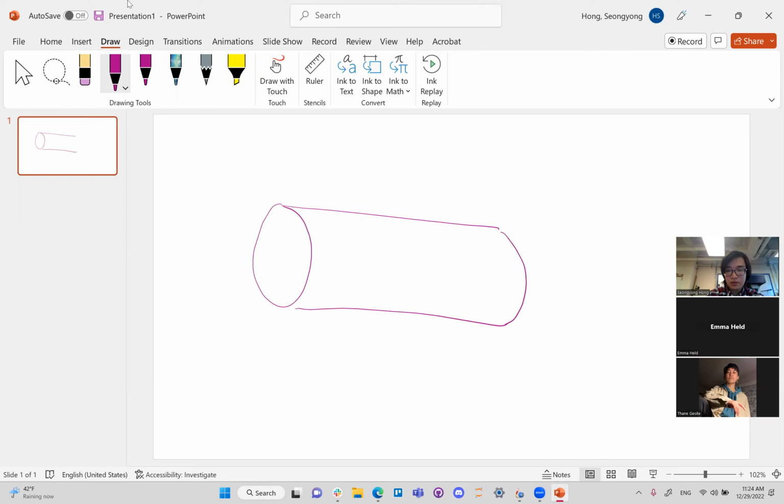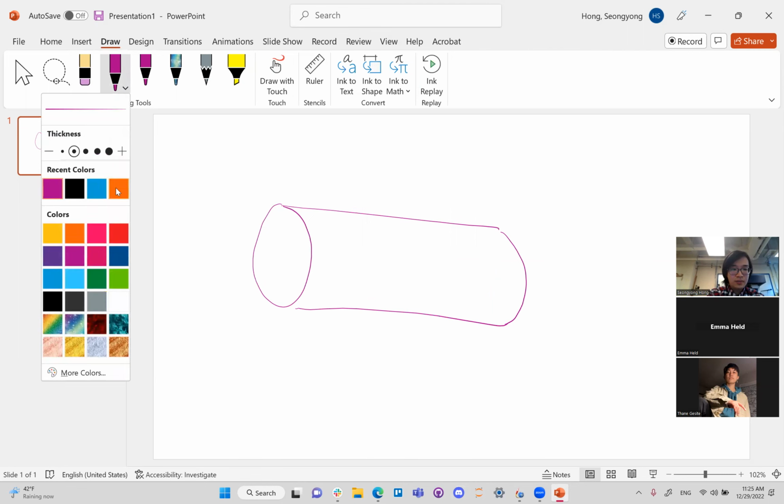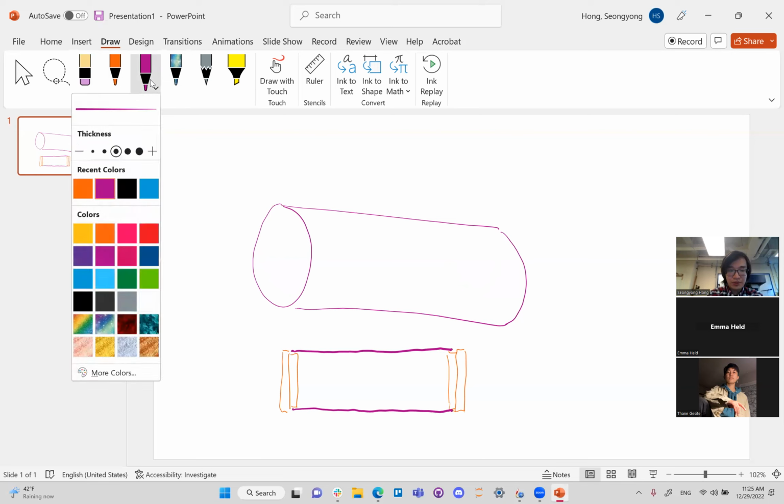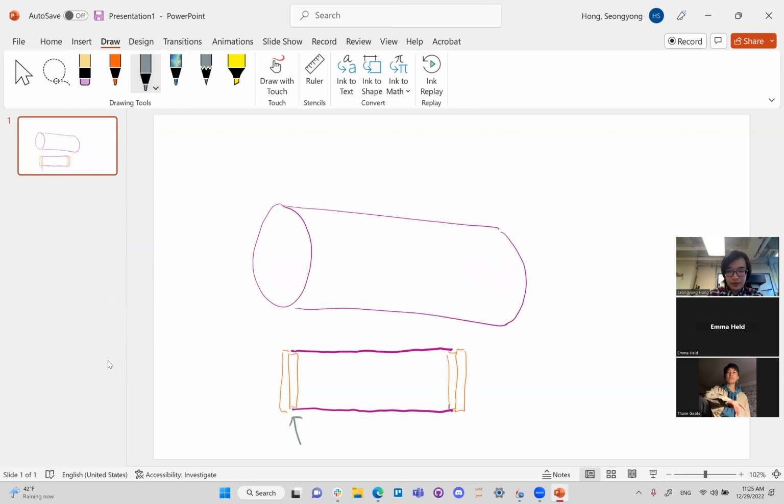I haven't really gotten that far yet. Well, you can definitely customize things, but a very default, common avionics bay design is one where you put your avionics in a coupler, so the purple part is the coupler, and you have two bulkheads, or a bulkhead with a whip, which you can see here, on either end, and you put threaded rods through them.